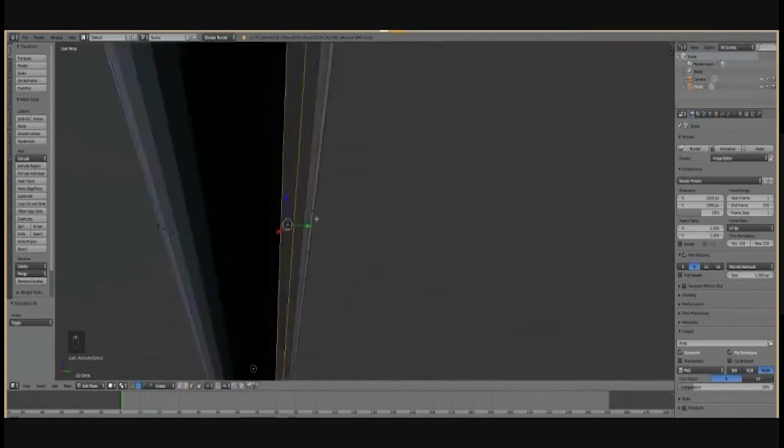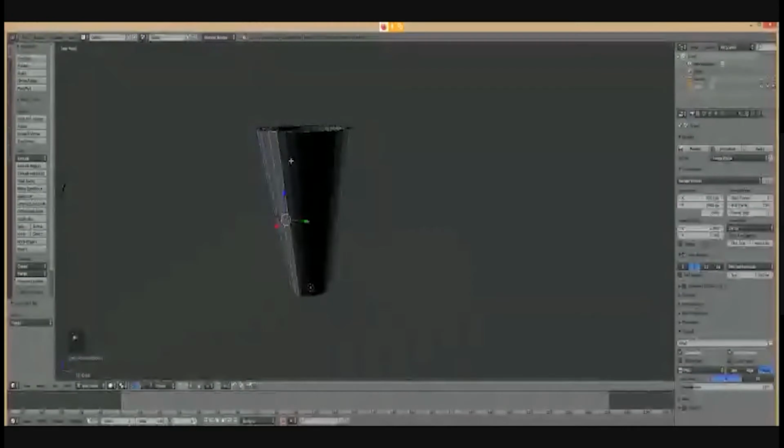What if I want to divide this into, let's say, three parts? I want it in such a way that there are three faces for one strip, right? Right now, it's only one face for one strip. Let's assume I wanted three faces. So 1, 2, and 3. The reason I want three faces is that from the middle face, I can extrude, and then with that extrusion, I can make a handle. That's the reason I want three faces instead of one.